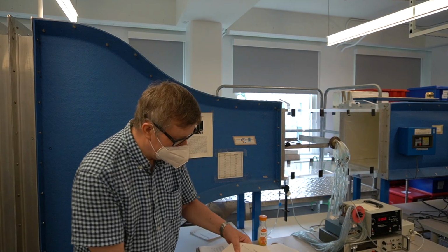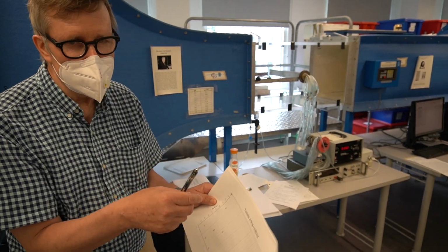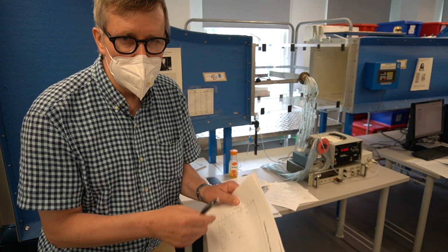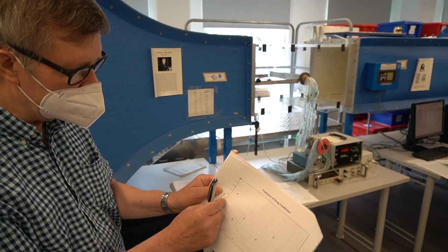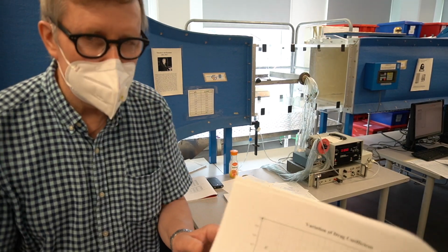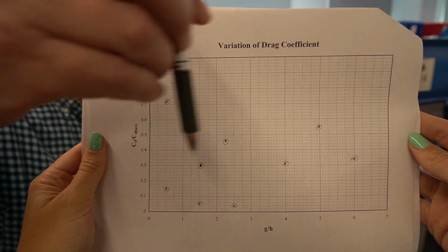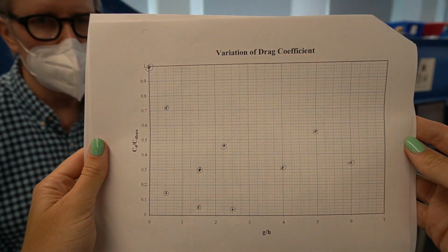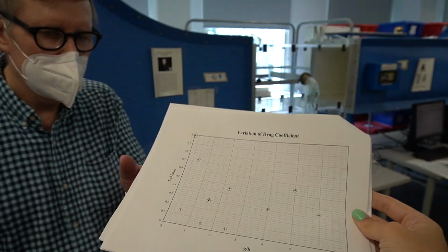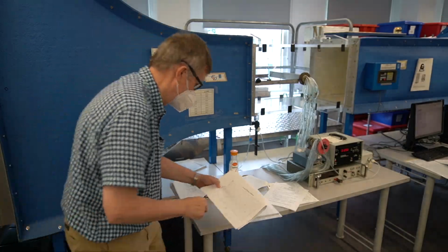If you plot all these things, CD for the cylinder with the plate in front, divided by CD for the bare case, is this CD over CD bare thing. And you can see that for the 13% plate and the 37% plate, it's such a mess, you almost can't find any curves to go through, but we'll interpret that for you right now. I'm going to put the curves through these data points, and you'll see what sense comes out of it.